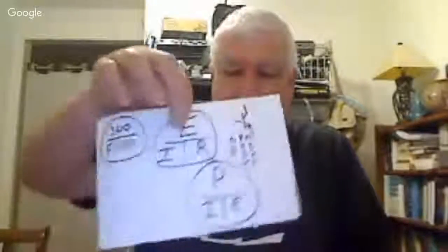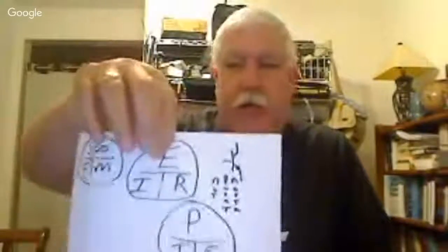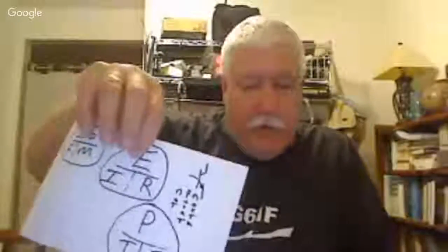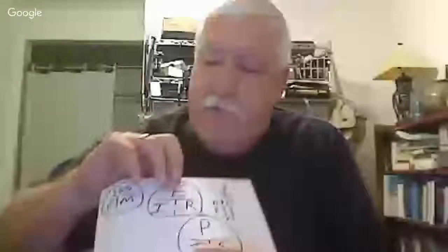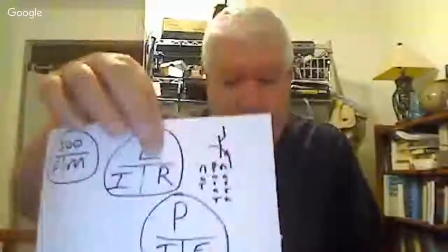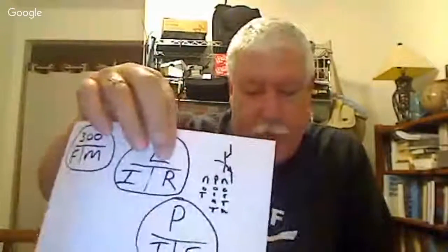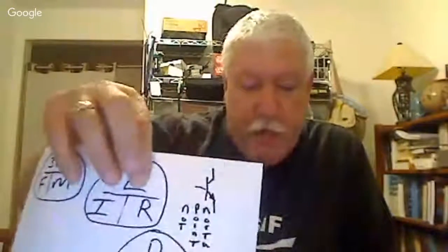All right. T5D10, what is the voltage across the 2 ohm resistor? Okay, now we're still using the solver, EIR. Electricity is renewable. What is the voltage across the 2 ohm resistor if the current is 0.5 amperes flowing through it? So they're asking for voltage. Cover the E. We're left with I times R. For I, they gave us 0.5.